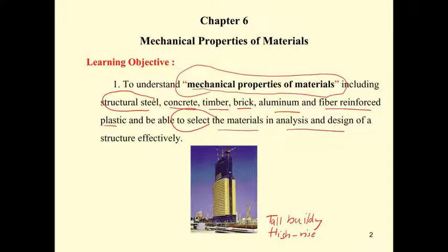And let's say it is constructed in the middle part of Thailand, such as in Nakhon Ratchasima. If you are an engineer, what material are you going to use? Since in Nakhon Ratchasima the soil is strong, unlike the clay in Bangkok, and our soil has strength, most of the foundations that we use are reinforced concrete with a slab foundation.